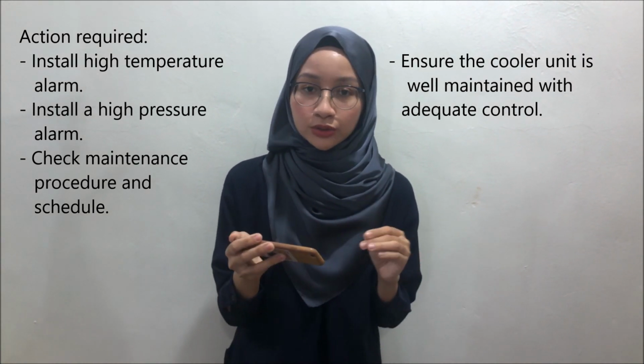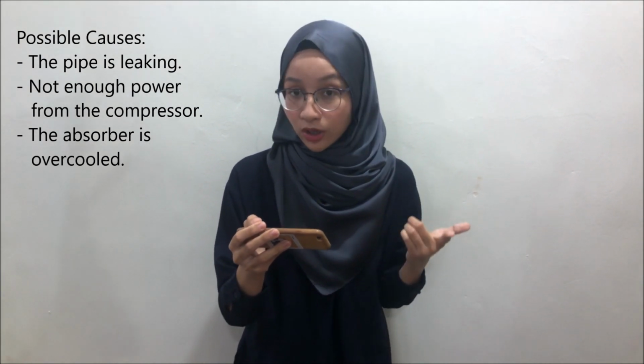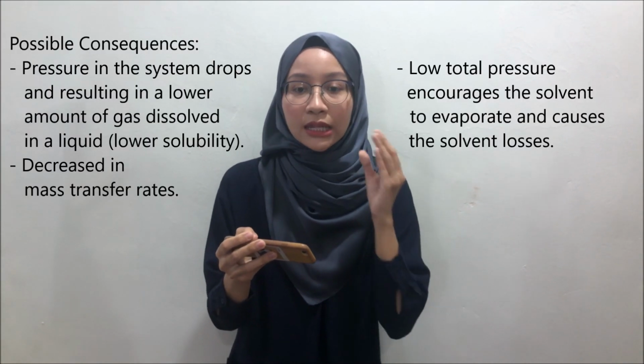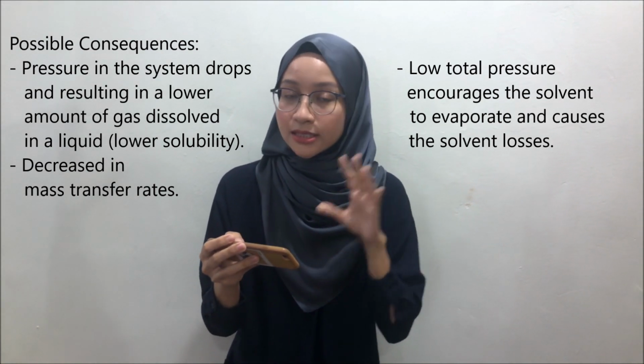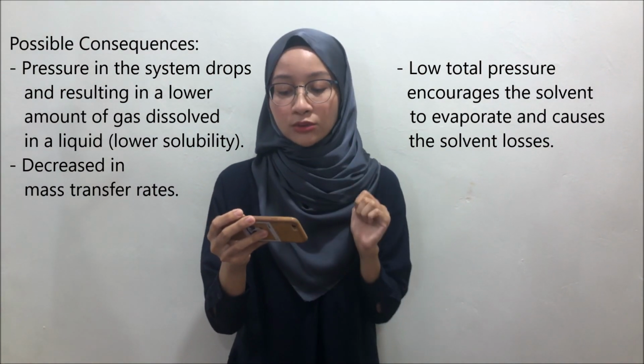The second process parameter is pressure. Low pressure may be caused by a leaking pipe, or not enough power from the compressor, also due to the absorber being overcooled. It will lead to a drop in system pressure, and also result in a lower amount of gas dissolved in the liquid, which also means lower solubility.